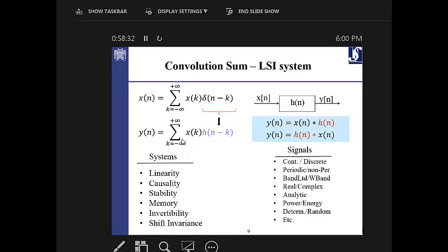And if you just get farther from the Gaussian, your entropy starts decreasing. It means that you have a kind of information inside the signal which is already extractable. Because entropy is the measure of information. So the Gaussian signal has the most entropy. It means that it's the most non-predictable signal. So when you see in the telecommunication that people talk about the white Gaussian noise, WGN, why do they talk about the white Gaussian noise as the additive noise to the signal? Because if they can solve the problem for the white Gaussian noise, they can solve for any other type of noise. The worst case noise is WGN. Okay?